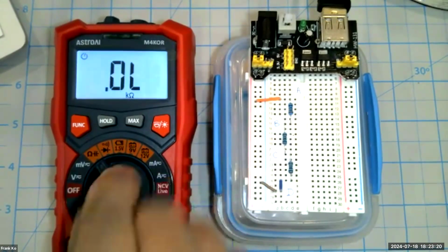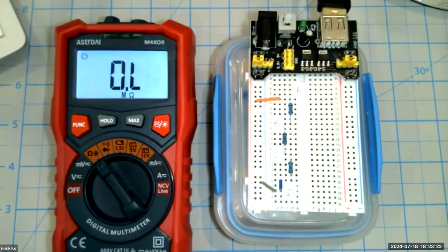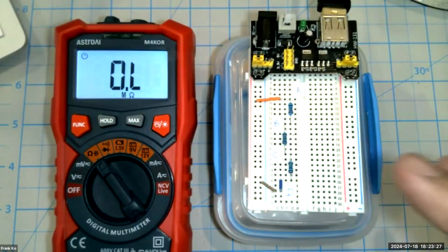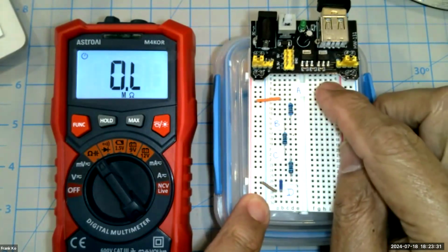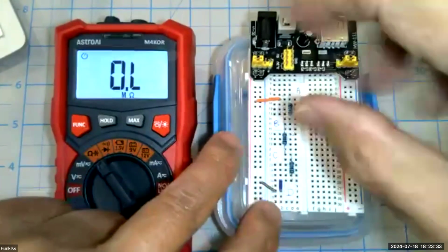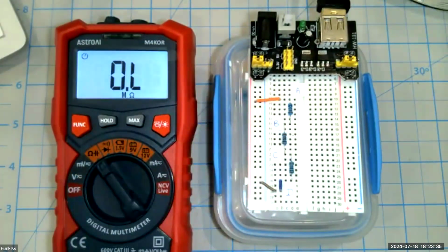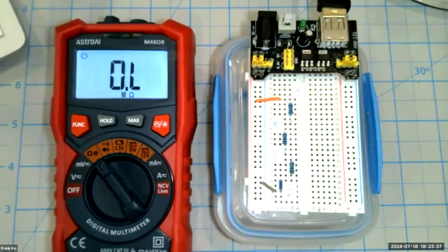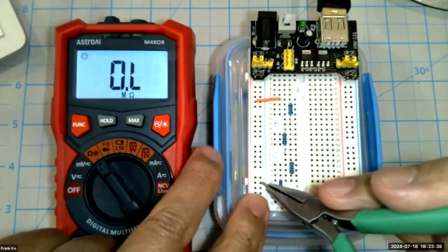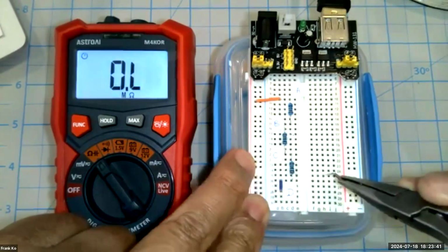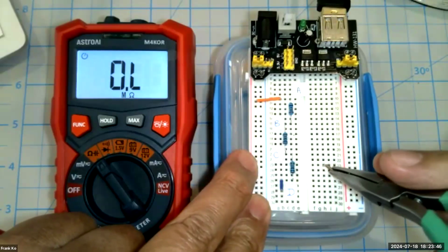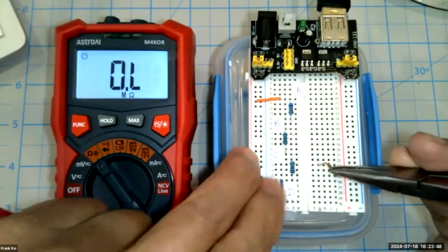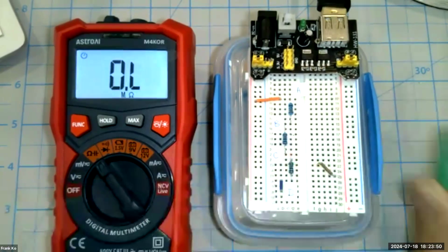Now we're going to test for resistance. Resistance was our first task. And so if you recall, you cannot measure resistances with the power supply that's on the board. So you have to disconnect the power supply, and we can do that either physically or we can just remove a jumper. I'm just going to remove a jumper. I'm going to take this, yank this out, and just park it. Okay, now it's parked.